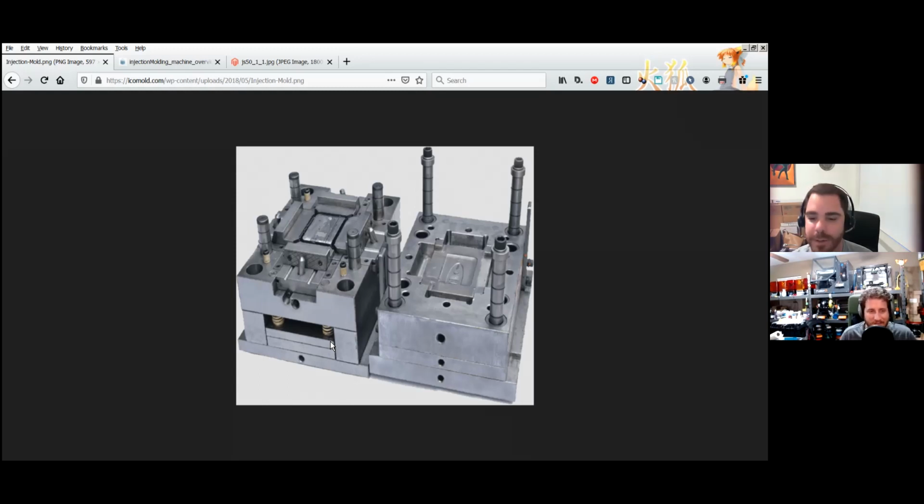The only other things I would note down for this is the surface finish on here is really interesting. For most of it, everything pretty much other than this backside where they don't care as much, and you can actually see, I think you can see the tool marks on the shiny side a little bit. That's where the mill that they use to make the mold cut its little teeth on there.